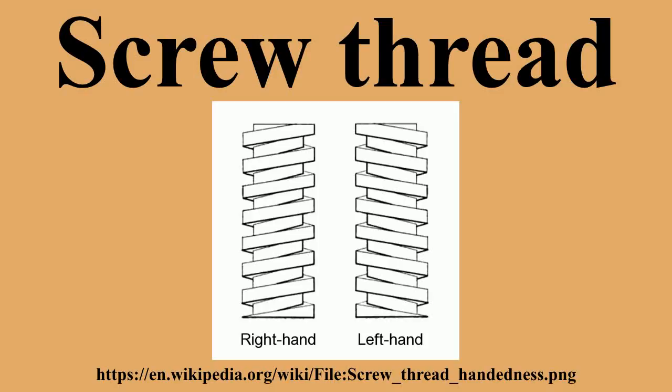The common V-thread standards include a coarse pitch and a fine pitch for each major diameter. For example, 1/2-13 belongs to the UNC series and 1/2-20 belongs to the UNF series. Similarly, ISO 261 M10 nominal outer diameter has a coarse thread version at 1.25 mm pitch and a fine thread version at 1 mm pitch.